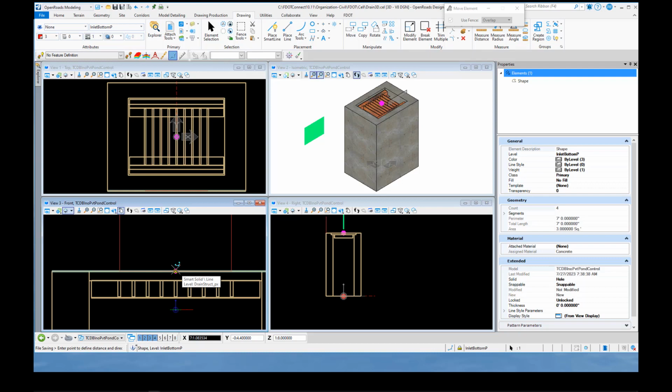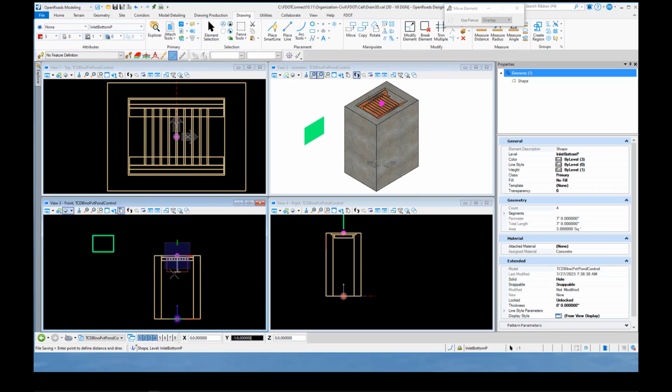Press the O key on your keyboard to bring up the compass origin. Then go directly down, hit the enter key and then the number 1 and click and open. You now have moved that to the front surface of the particular wall we're wanting to cut.